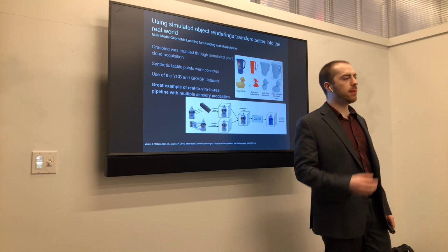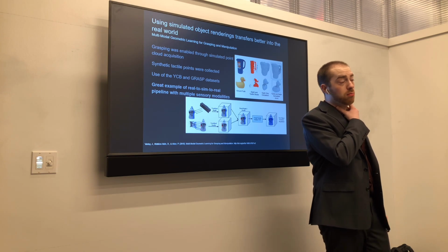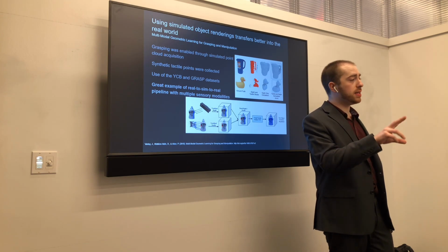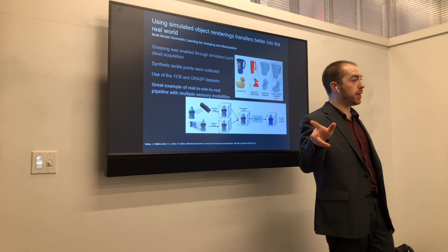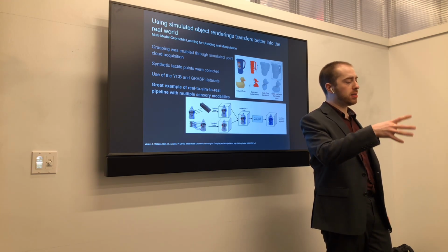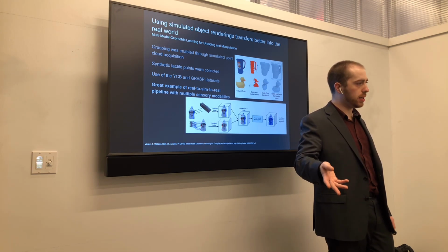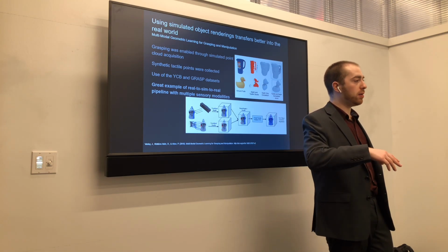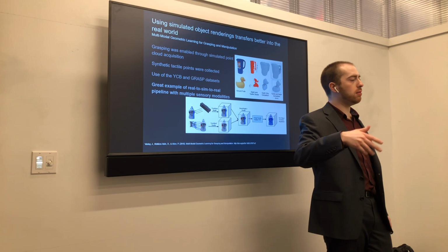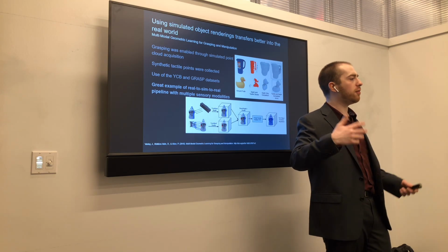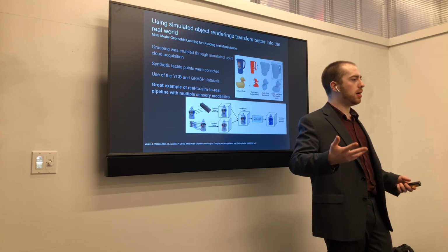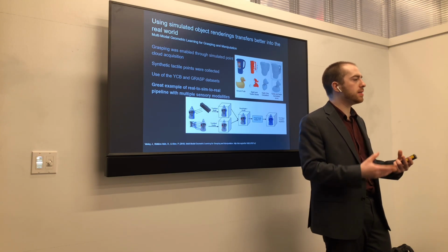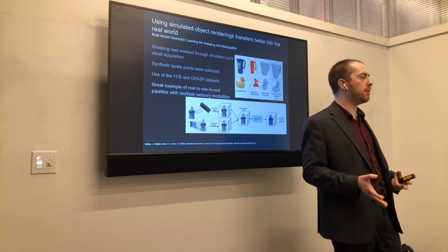There's another paper that came out March this year. They were doing sim to sim and then sim to real. So they mapped the simulated image onto a simulated image and then mapped a real image onto the simulated image using domain randomization. And then that offered a much more realistic grasping simulation because they were just operating in that simulated image environment.